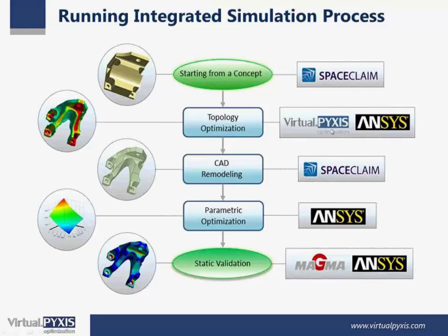And after that, I will show how to apply the topology optimization, integrated to ANSYS, and you get a final result, something like that. After that, in this case, we used SpaceClaim to remodel this new design after getting the STL file of the optimization. SpaceClaim is from the ANSYS group, is an ANSYS solution. You get a very fast condition to remodel this new design.